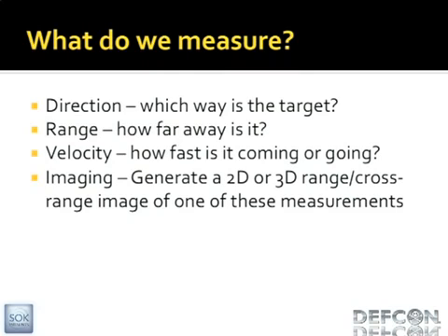And when I say range and cross-range, what I mean is, in the radar world, if you take a picture of like this wall, for instance, or that wall, whatever, your two dimensions are like up and to the side. They're both perpendicular to you. A radar flips that 90 degrees. So one of your dimensions is range, which is how far away the thing is, and the other one is in some other axis. So it's cool because you can look from the side and then get kind of an overhead view of what something looks like.